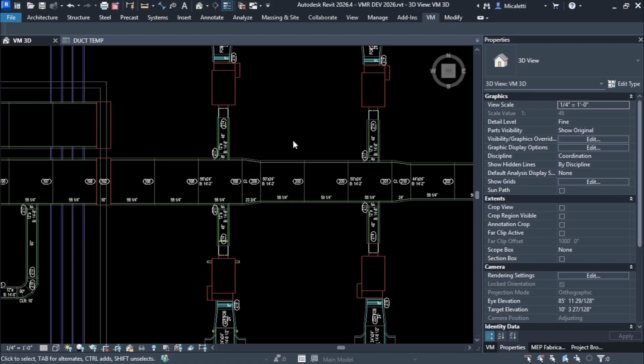Well, some of them try to sell you some snake oil and smoke and mirrors, and they'll say that they're auto dimensioning spools. Nobody's doing that, and the reason I know that is because I've been in the industry 25 years. One of the challenges with batch spooling 50, 100 spools at once is that what is a good view direction for one spool is not necessarily a good view direction for the next spool. When you're just dragging a box around 50 spools, they might say they have an auto dimension tool, but that wholly depends on which way you're looking. Does the dimension need to drag this way? We can get into that later if you want to get into the spooling stuff.